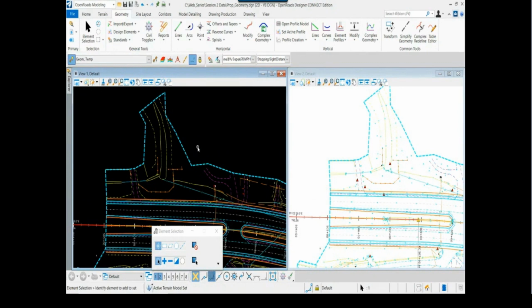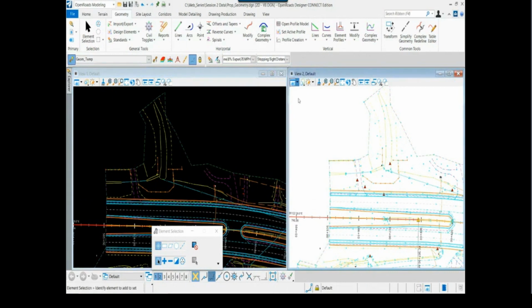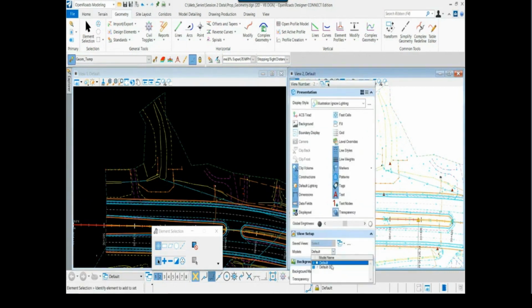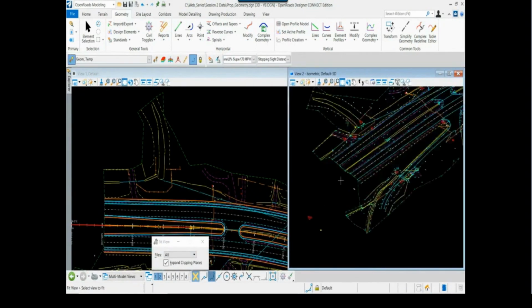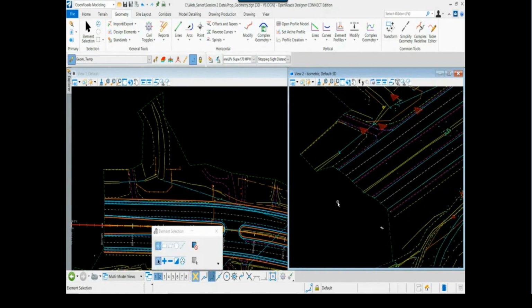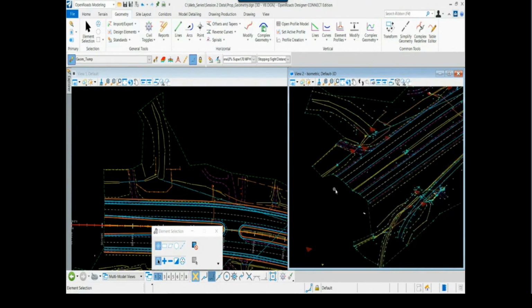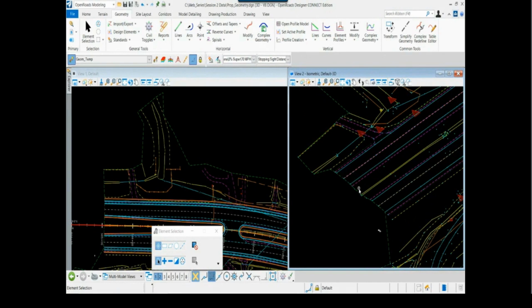Not only does it set the terrain model active, but by activating any design element that has 3D in it, meaning some sort of elevation definition, OpenRoads Designer also creates, and does this for you, a three-dimensional model and moves all of the project data into it. So now the data that I referenced to my original 2D file has been placed in a 3D model as well. So the elevations from my topo, the elevations from my resulting terrain model, all that data is in a 3D model in my DGN and available for me to use. Okay?